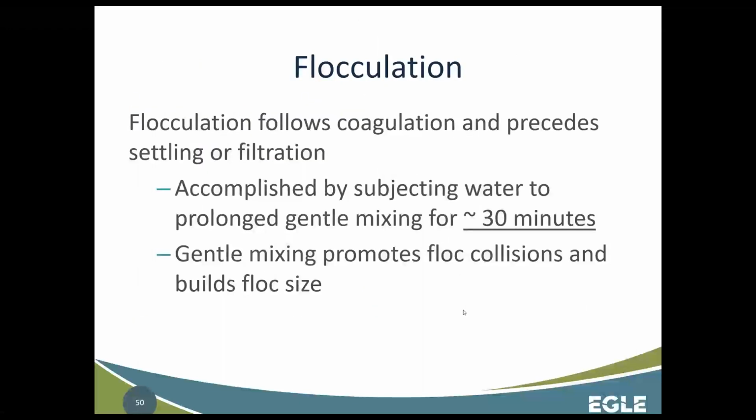All right, we're going to move on to flocculation. Flocculation follows coagulation and precedes settling or filtration. So again, conventional plant: flocculation, then you move on to your settling basin, plate settler, whatever it may be, a settling step. Direct filtration, you're going to skip that settling step and go straight to filtration.